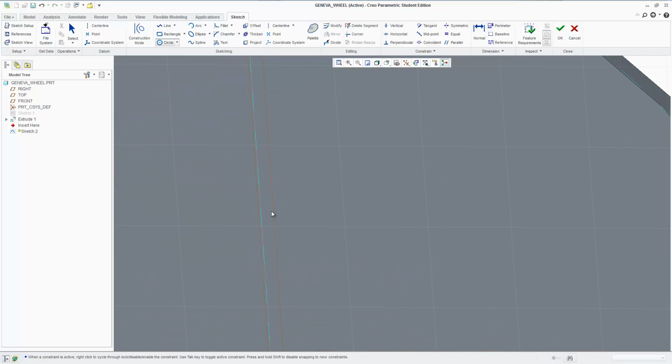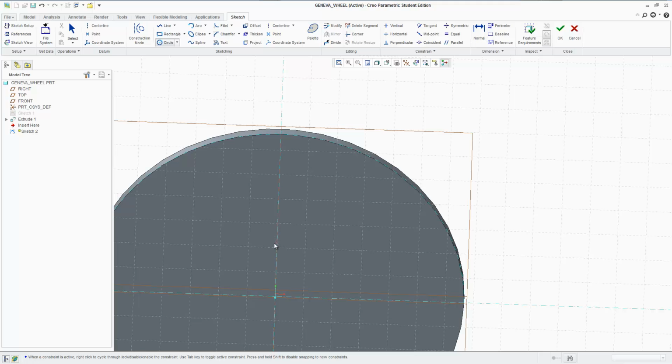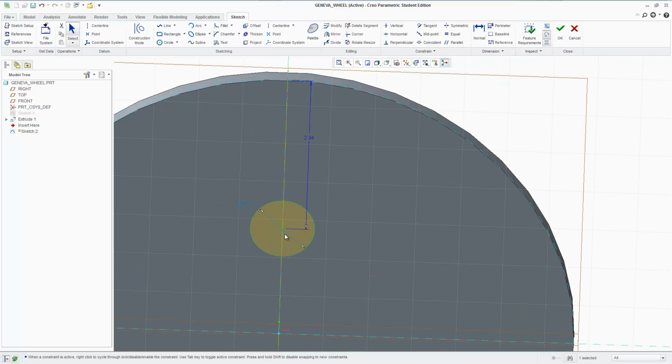And that's I guess a good way to demonstrate the use of construction lines, because to get to that point it would be kind of tricky, and this way I can control it however I want. See, now I have the circle here, 1, and now I can just control where it is by just saying this 3, and I can say 1, and it moves wherever I want it to, and I just have to change one dimension, and that's why it's kind of nice to use construction.